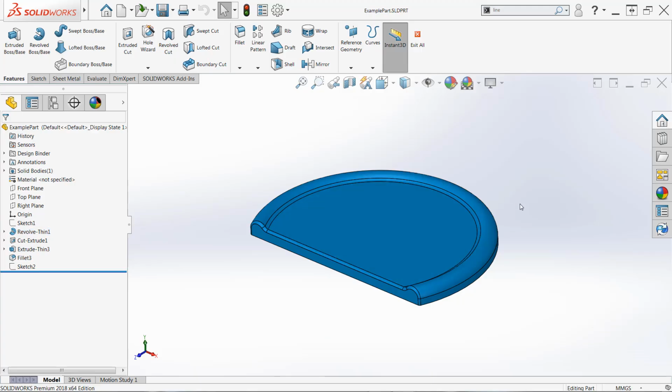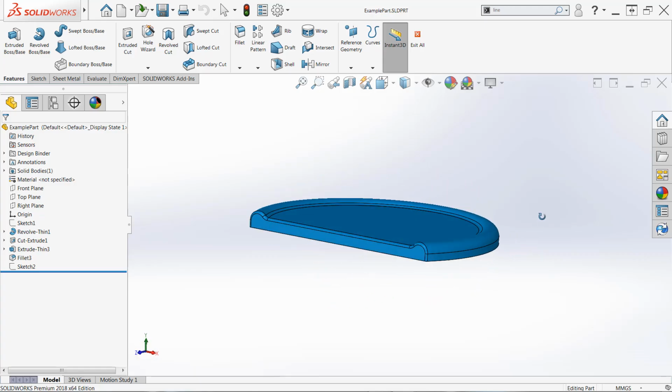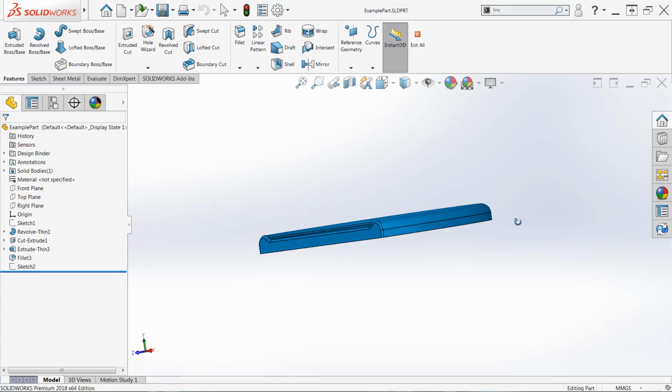Now to rotate a model, and this is a really critical aspect for new users, you need to be familiar and understand how to rotate and zoom and everything else. And rotation is probably the hardest to grasp, so you want practice with that. To rotate a model, you're going to click down on the center mouse wheel as if it were a button, and then drag around on the screen. And you can see I can rotate this around freely.